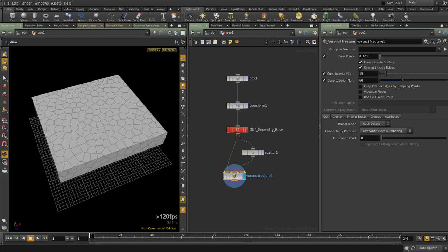Rigid body is very fast, is based on bullet, and is very good for simulation. Bullet is very accurate, fast, and good, and you can use it without problems. The FEM is the finite element material solver, based on the characteristics of my material, and is very realistic but very slow. So I prefer to use the bullet system.